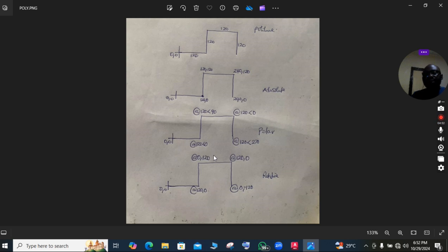That's how you do it till you want to get this one now. This one relative to this point will be @0,-120, because the y is traveling against, just like driving against traffic. You put the negative to show that it's going down, the negative y direction. So that is that about that.